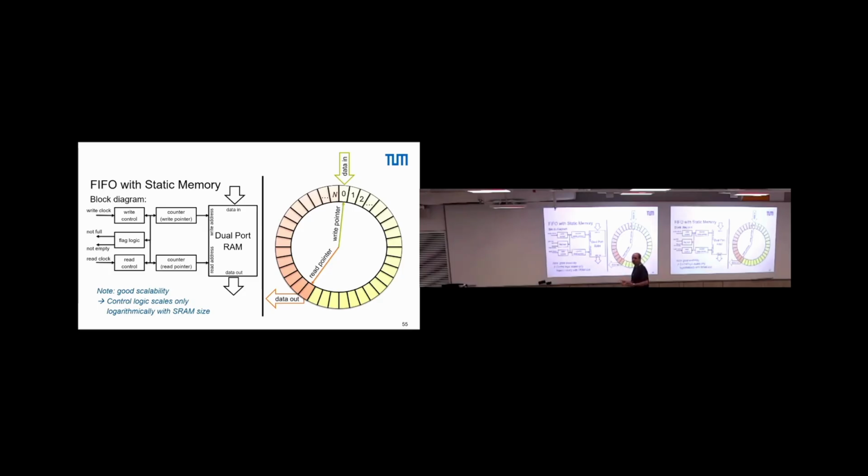Quite straightforward. And the simplicity of the design, and that it scales well, makes it actually the choice today. So you have just a piece of SRAM. That is something you can just put on your chip. You have two counters to implement, and you have this little bit of logic here. So still, this is an asynchronous FIFO.